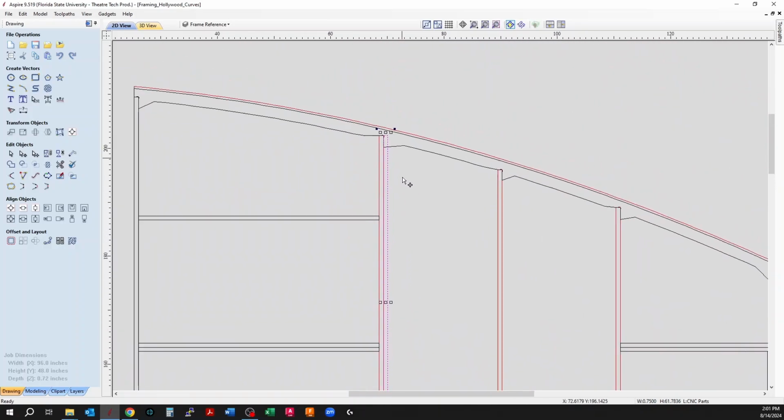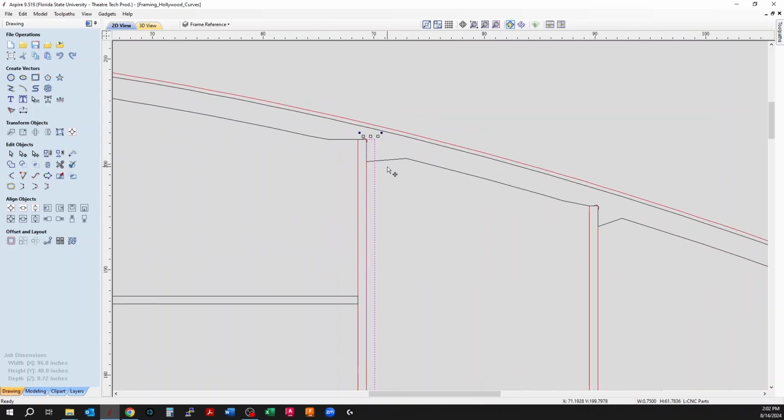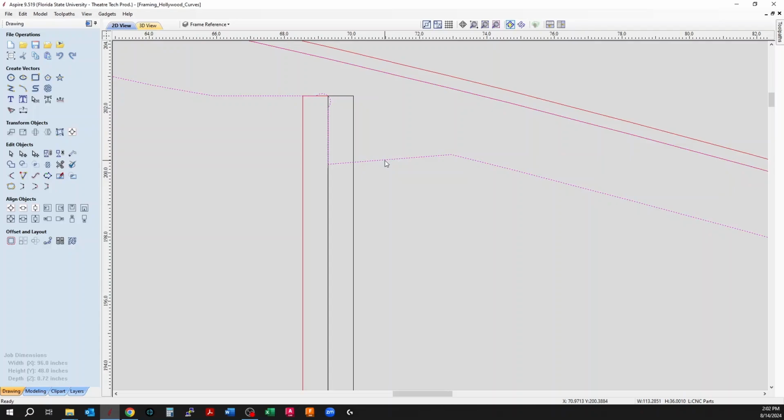And then you just want to come back and modify your node, right? So with this, you can go back into your node edit tool. So I kind of did more than I needed to with that, right? Because I don't need it that way. So I'm going to delete this point, D for delete, move that over there, right?